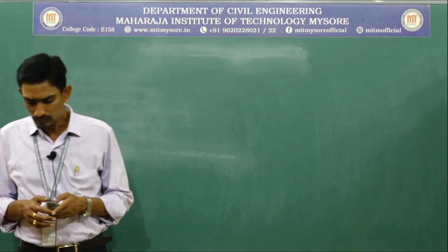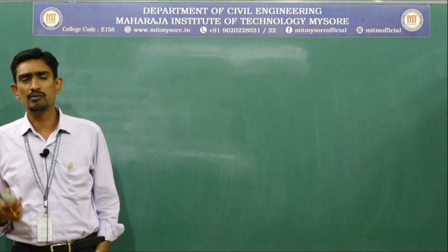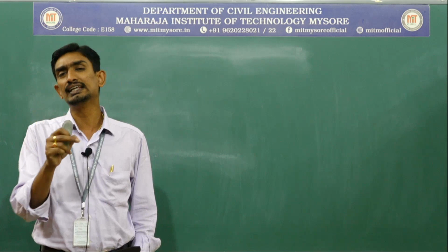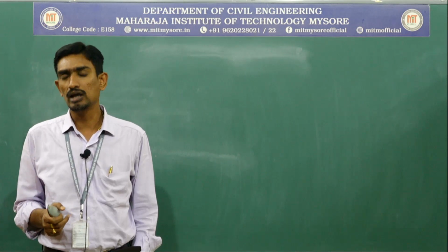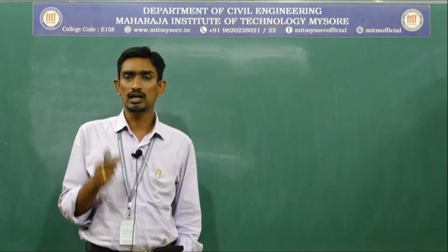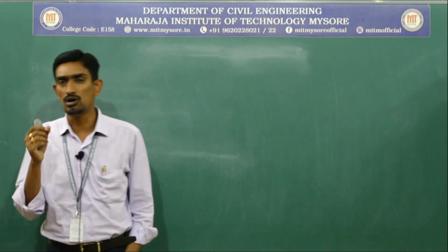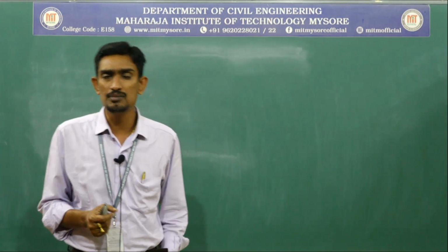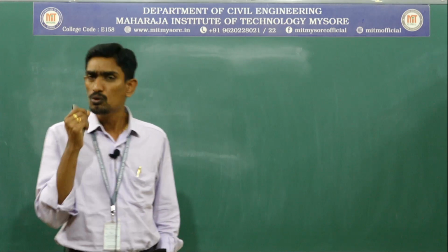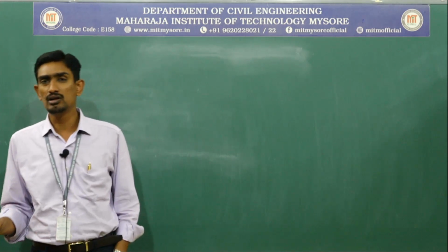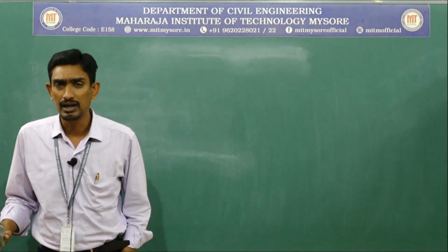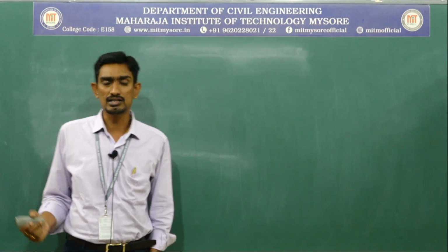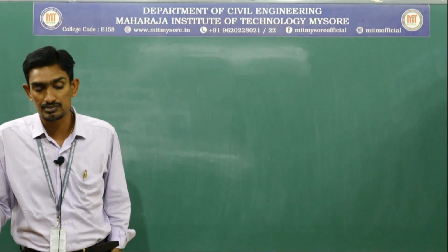Why does it prevent fire better? Because chemically bound water is present inside the gypsum. The chemical formula of gypsum includes water. That chemically bound water inside the gypsum is a boon, which will prevent the fire, so we can say it is a fire resistant material. Next, the second point, the thermal properties of gypsum.